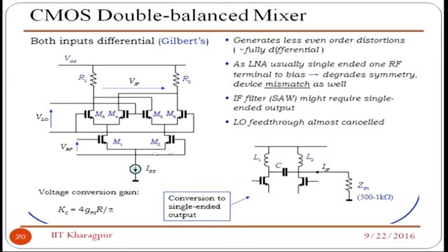Typically, you know that this Gilbert configuration first started with the BJT model, so exponential current. They are adding the current in both the loops in such a way that you will ultimately have tan hyperbolic functions. If you look at the book Gray and Meyer, there is a fantastic chapter on the mixer, where you will find how it has been analyzed in the case of a bipolar junction BJT based mixer. Please go through that. Don't go to the Gilbert cell just by this MOS, but go to the BJT side. Very well clarified, very well defined.